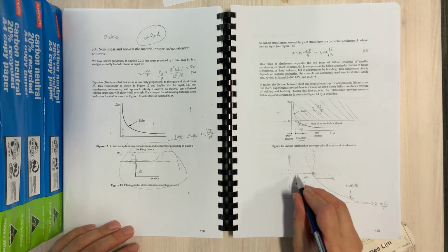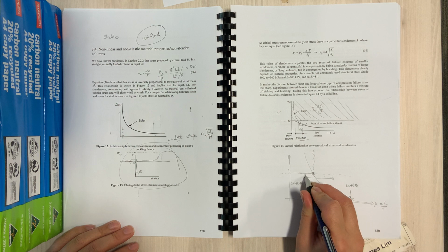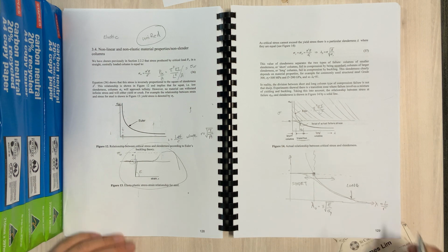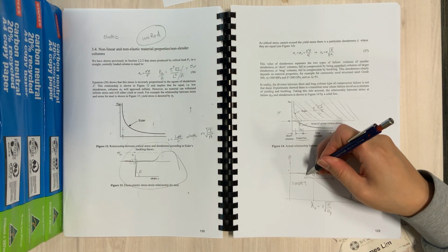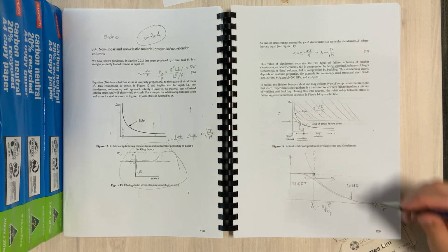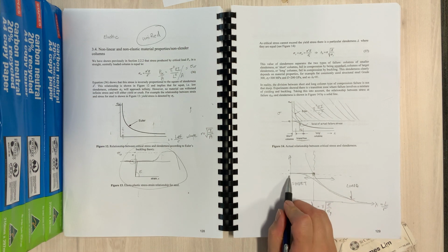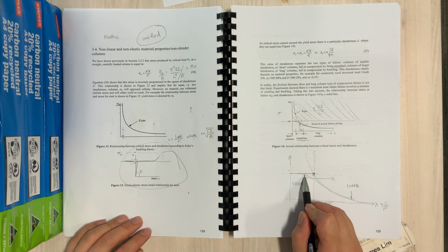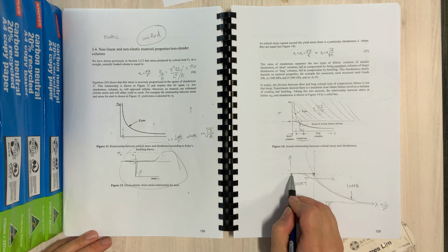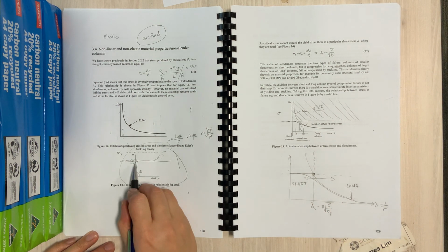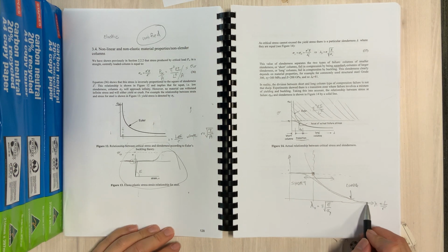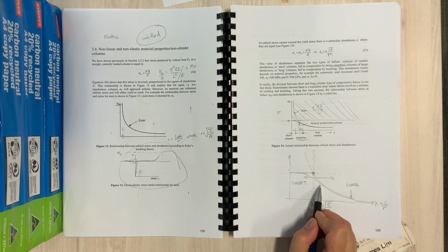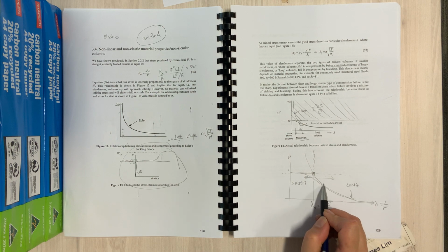In reality, maybe there's a smoother transition in nature between the short and the long, and then it would gradually go there. So maybe this is the true behavior. In nature, things don't just become sharp. You tend to get smooth lines, and of course columns are in nature, so you would expect a smooth line between the short and the long. Here at this end, of course, it's going to fail through sigma y, and at this end, it's going to fail through buckling, and then we would expect a smooth transition, not a sharp transition, which I've just sketched there.